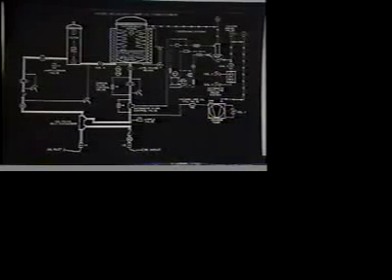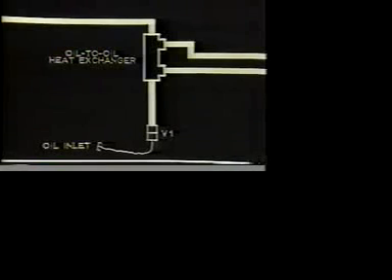Let's examine this schematic of a modern vacuum dehydrator. The lube oil, which comes from the bottom of a reservoir, enters at this point here, goes through an oil-to-oil exchanger because, remember, the purified lube oil here is at an elevated temperature, higher than the incoming oil. Consequently, if economics suggest that we do this, we have the option of putting an oil-to-oil exchanger here to economize somewhat. We go with the oil into the vacuum dehydrator through this particular pump.